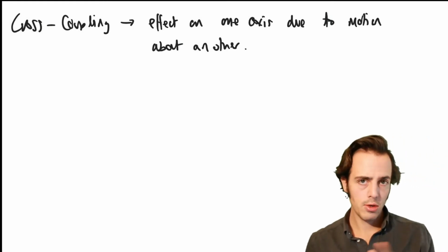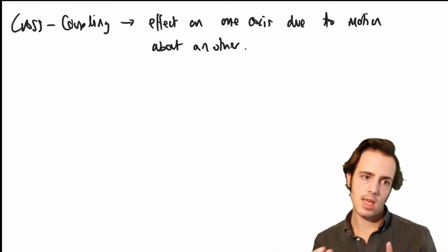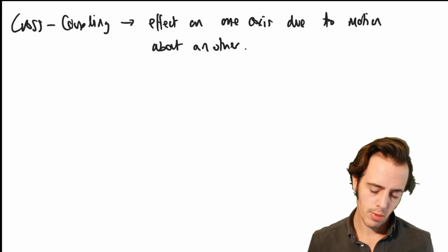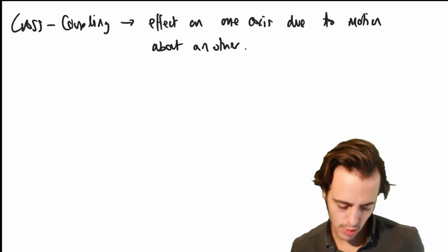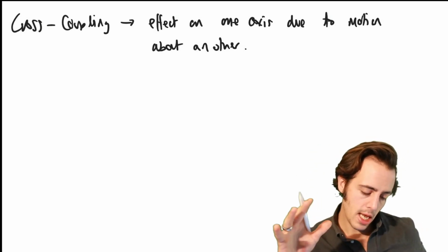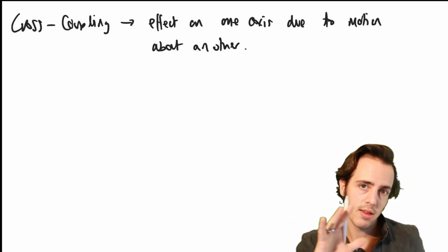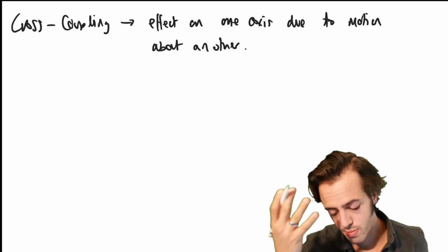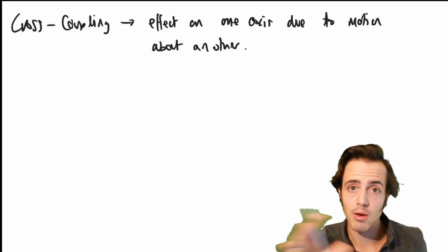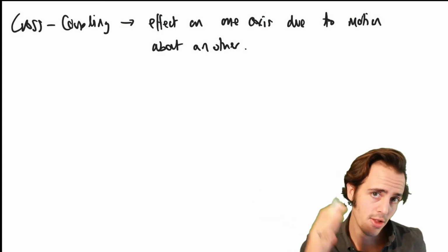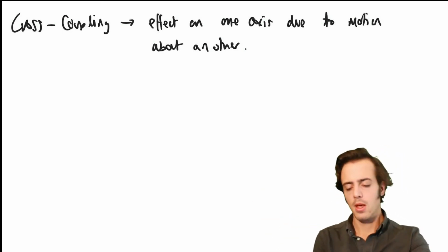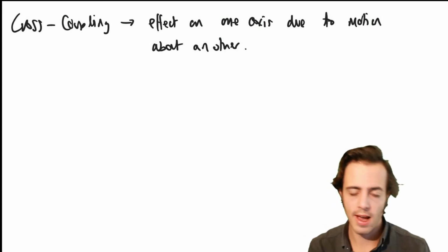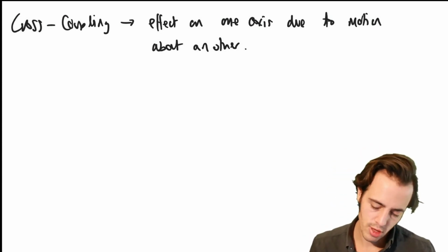We're going to look at two different forms. We're going to look at the aerodynamic cross-coupling, largely due to the vertical tail, and we can look a little bit at the wings as well. And we can look at the effects due to having a gyroscope on the aircraft. If we have a propeller or a big gas turbine engine, this brings in gyroscopic precession, which causes an off-axis motion that is somewhat counterintuitive.